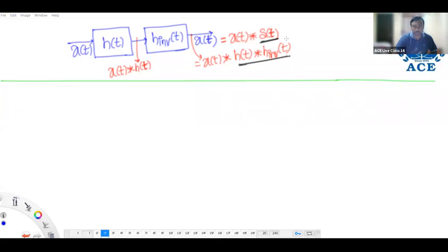Pawan, what we learned under invertibility? Just recollect. Once the system is invertible, then only we can find the inverse. You should take x(t), we should recover back x(t). That is the reason the output of the second system must be equal to x(t). But instead of a general system, now we are checking that for LTI. So what is the conclusion? x(t) convolved h(t) convolved h inverse of t is delta(t).